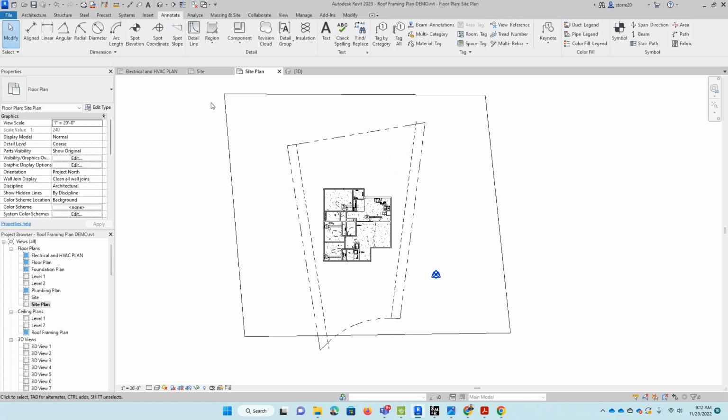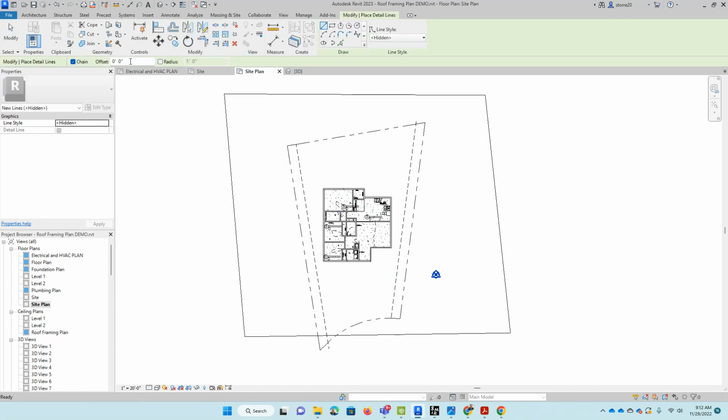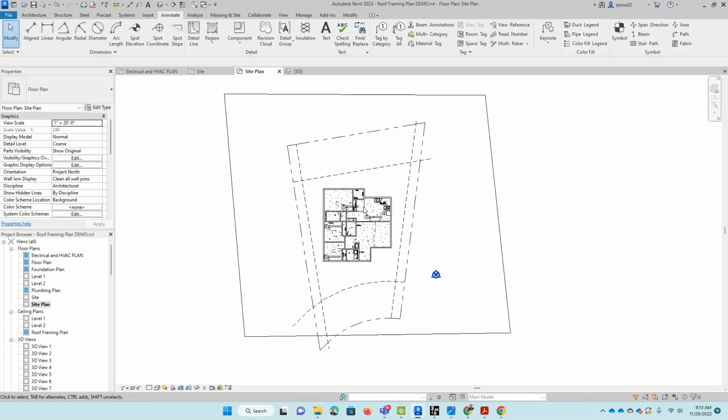And then from this point to this point right there. And then I'm going to, once again, pretend that it's a 20-foot offset, front and back. So I'm going to draw this one, I'm sorry, setback, right there. And then my arc, the 20-foot, is going to start at this point and at this point, and it's going to be on that point there. All right. Using my trim command, I want to trim these lines to start showing the conceptual setbacks.